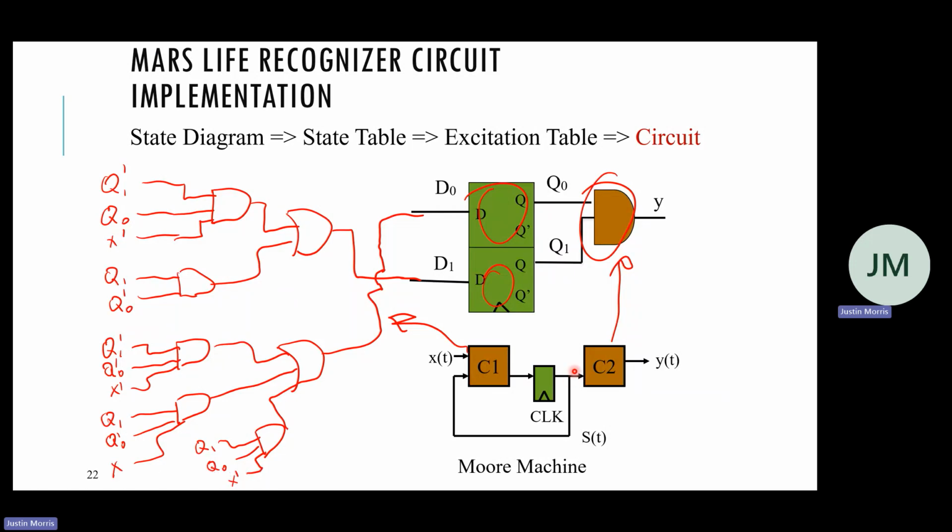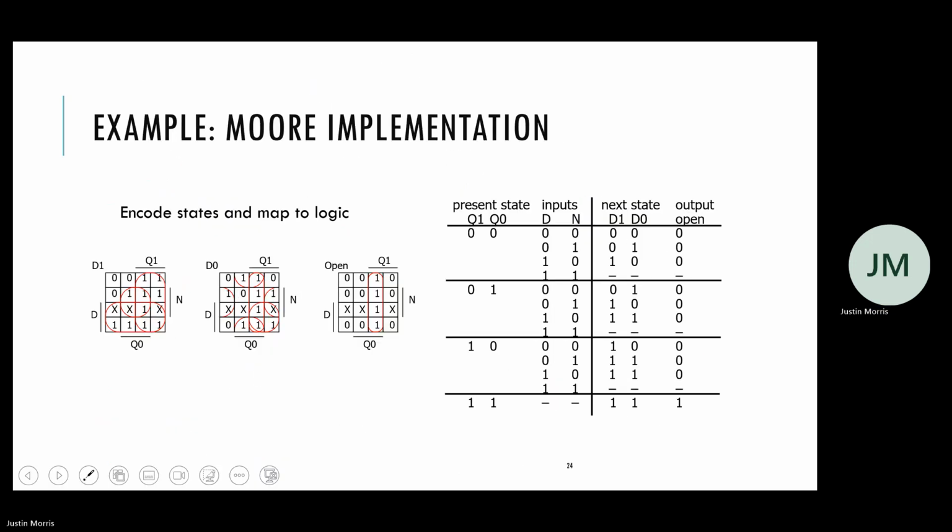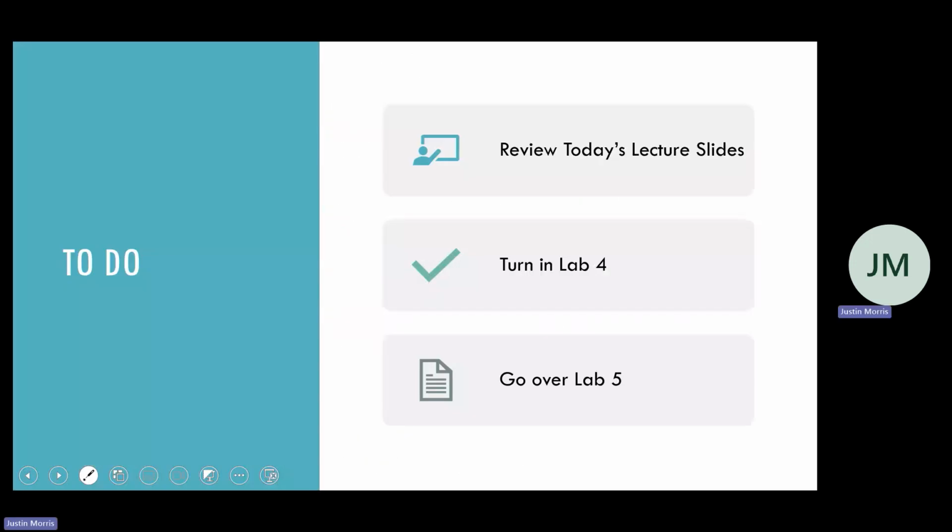Okay. I have register outputs going into some combinational logic, back into a register. I have to satisfy the setup and hold time here, going through combinational logic circuit 1. Combinational logic circuit 2 is not as important, right? It just goes to outputs. Why? It's not going into a register. All right, so that is the slides for the introduction to finite state machines.